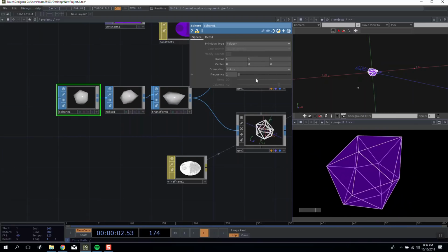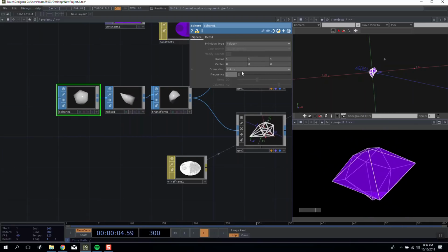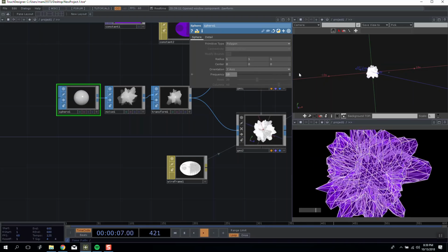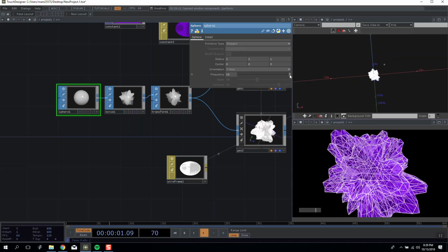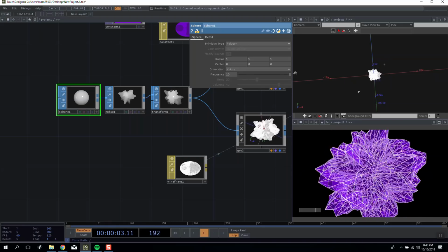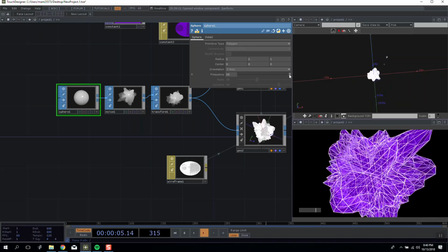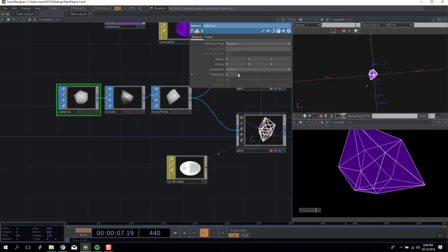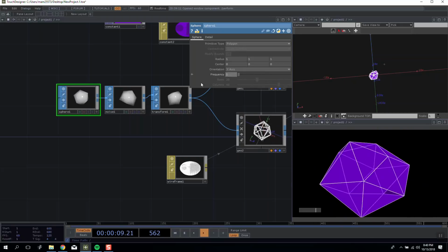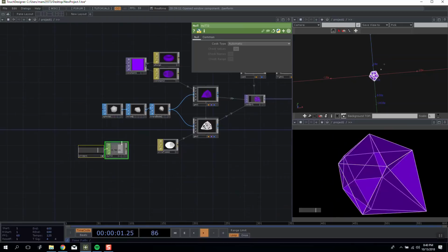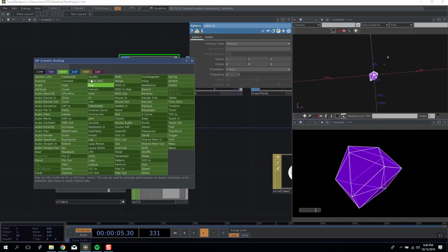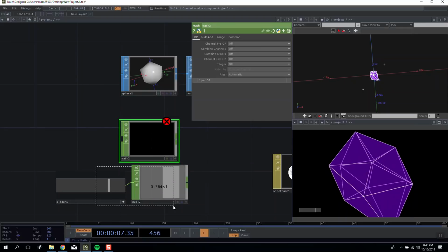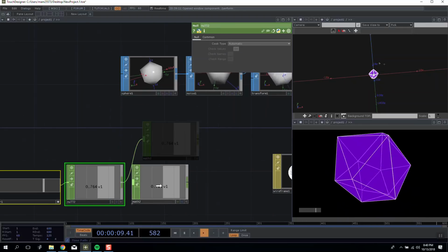So it goes from being this super sharp, low poly shape up to this amazing sort of complex, almost biological form. And to do that, I need to change the frequency of my shape between 0 and 1. Now, this is coming out between 0 and 1, and I need it between 1 and 10, excuse me. So the simplest option for that would be null into a math.